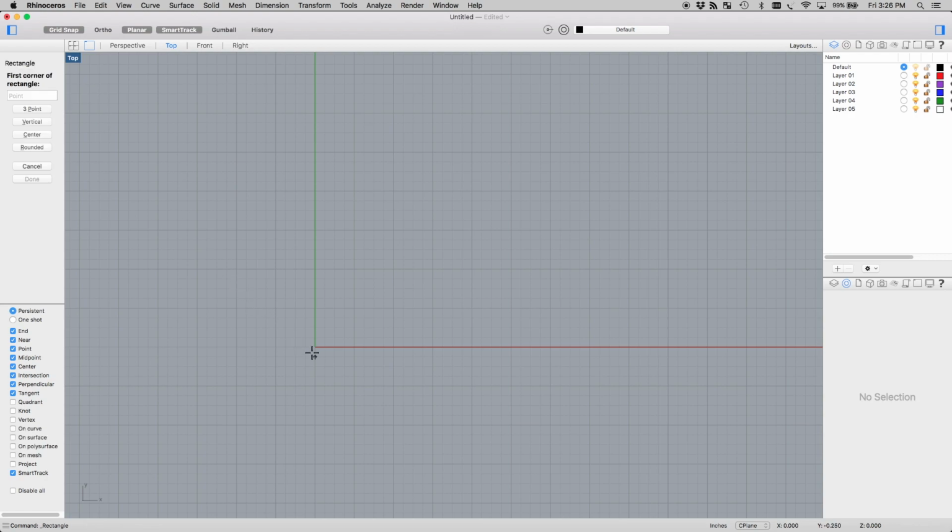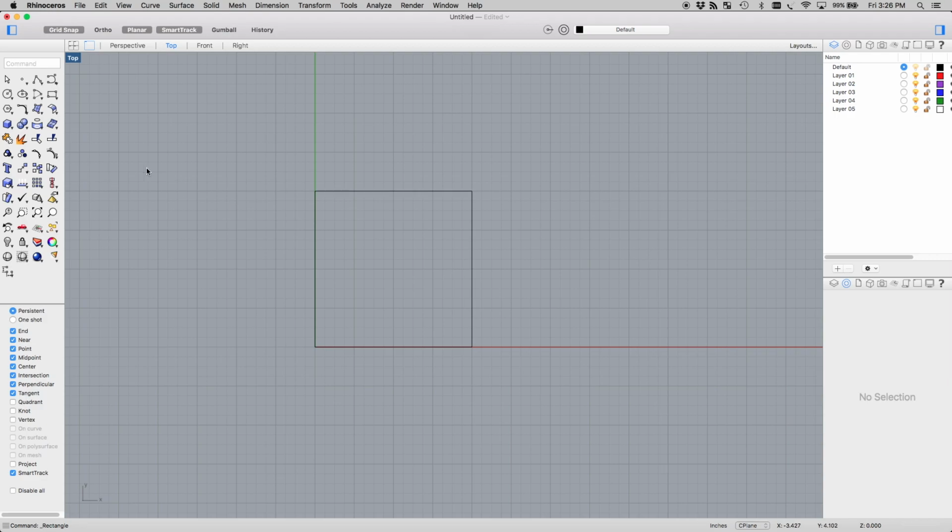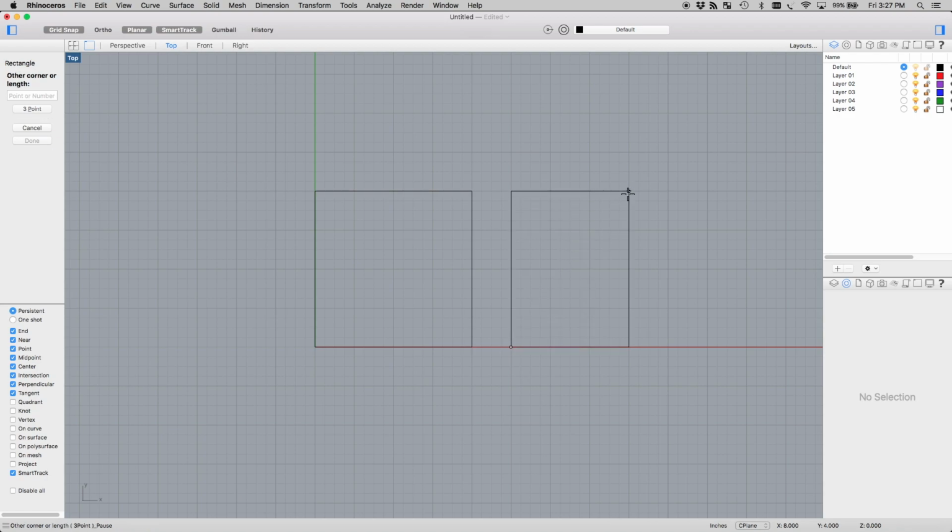The rectangle command works similarly to the line command, but creates a box using the 2 coordinates that I've selected. This is also a great time to highlight that any button with a small drop-down arrow next to it has additional similar options if you click and hold. To explain this better, I'll choose the rounded rectangle and create a rectangle like before. But this time, I'm asked to perform a third step to define the radius of the corners. As usual, I can use grid clicks or the command line to finalize the step.